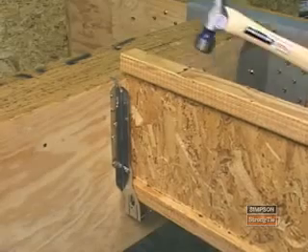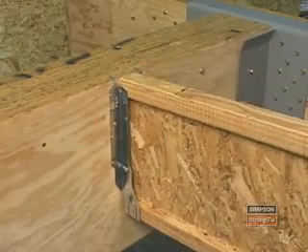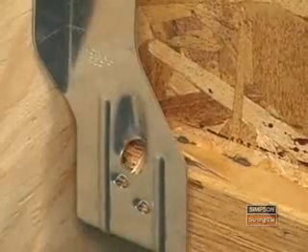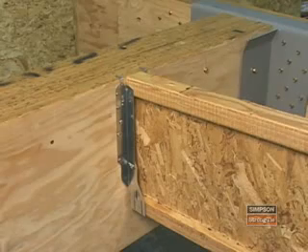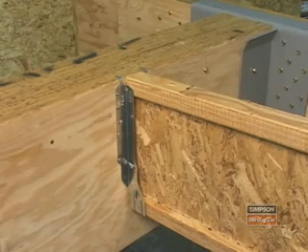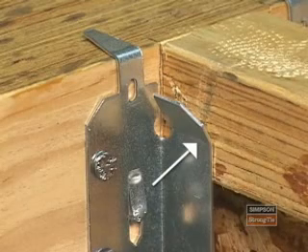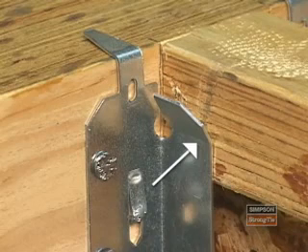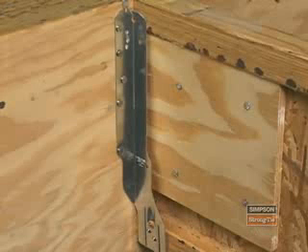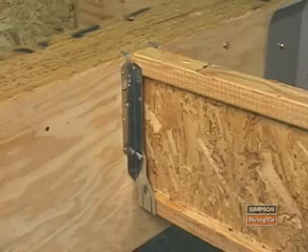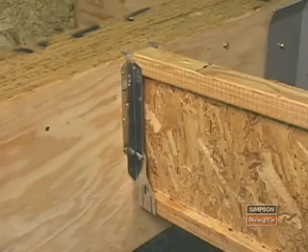Note that when you place the joist in the hanger, you must make sure it snaps into place past the teardrops in the seats. You may have to hammer the joist to ensure this. Don't try to pull the joist out of the hanger after it is snapped into place. Also make sure that the side plates reach the top flange of the I-joist. If additional uplift is required, add web fillers and drive 10 by 1.5" nails to the triangular holes in the side plates. Here is a correctly installed IUS series hanger.